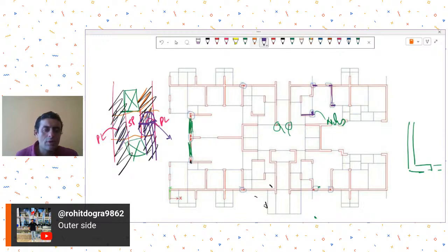For shear you cannot do much, because if it is failing in shear, the only option possible for you is to revise the concrete cross section sizes. So in such cases you may have to either go for increased wall thicknesses, or go for a dog-bone shaped arrangement where you locally thicken these corners and provide a smaller wall depth in the central portion.